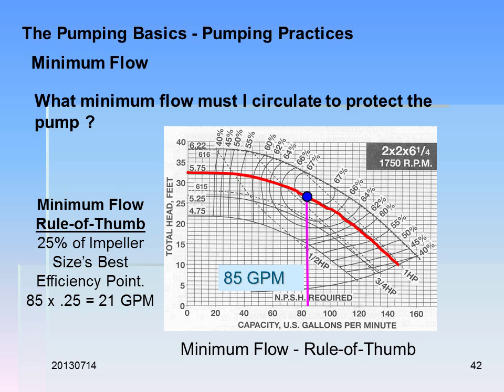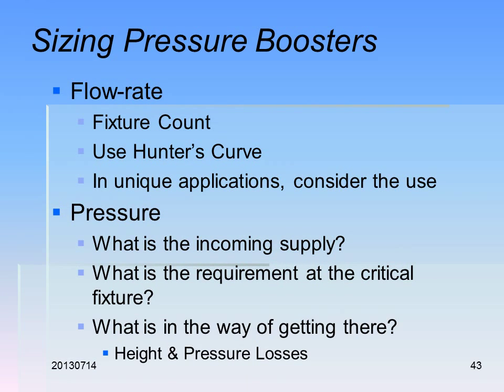We don't want to flow less than that because we're going to be in danger of damaging the pump in an unsafe condition.